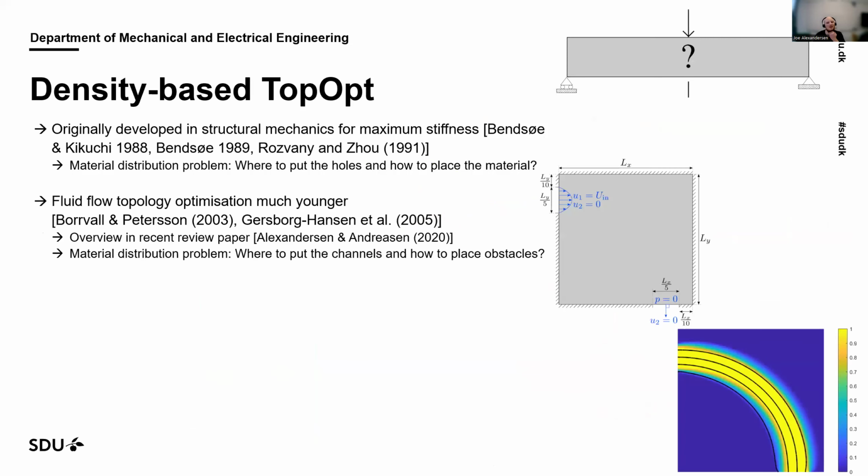But in contrast to the structural problem, where the problem is sort of where to put the holes and how to place material, the material distribution problem becomes where to put the channels and how to place the obstacles. So same question, phrased slightly differently.